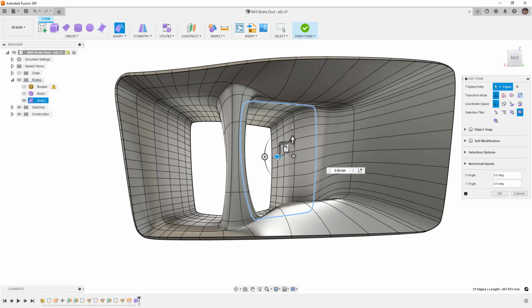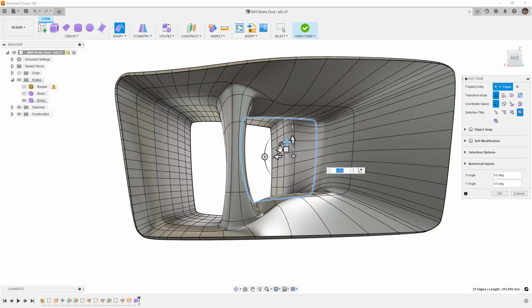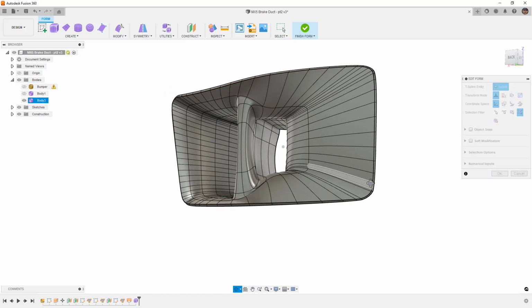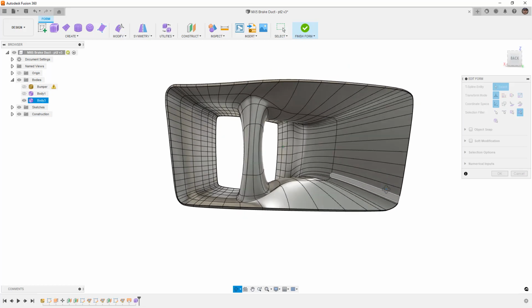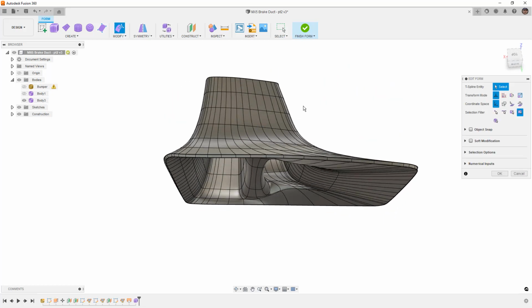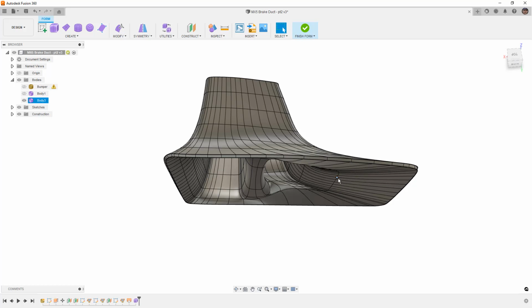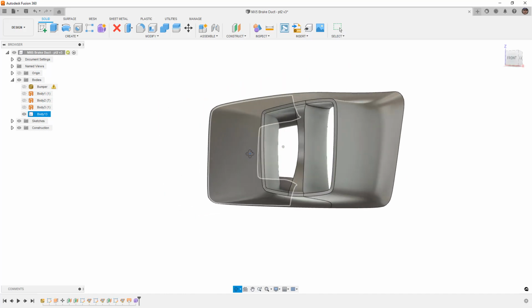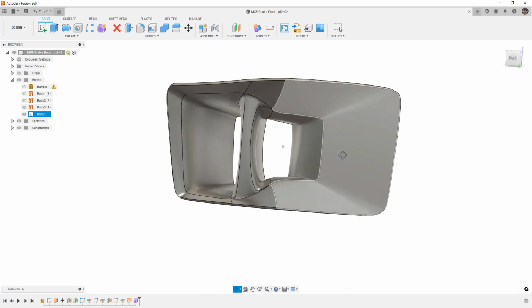So these are all things that, again, are extremely important, and it's really difficult. So I don't suggest that people dive into using the Thicken modeling approach with freeform models until you get really comfortable using them on just surfaces. It's much easier to do this after the fact with solid or surface tools and not do this with freeform tools just because of the extra layer of complexity that happens. But it is possible, and maybe this will give you some inspiration or some insight into how you can apply this to yours.